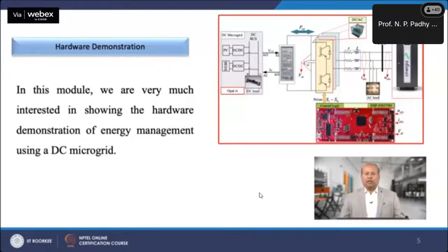Now, the analog output of the power amplifier is given back to the analog input of the Opal RT controller. This input signal is the input to a current source connected at the DC bus of the DC microgrid. Here, the analog output of the power amplifier is the current signal that either feeds or draws from the power amplifier.